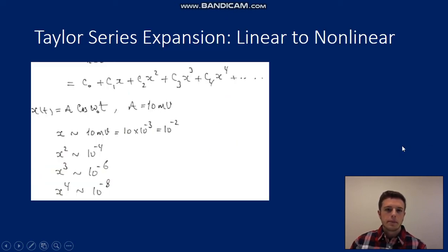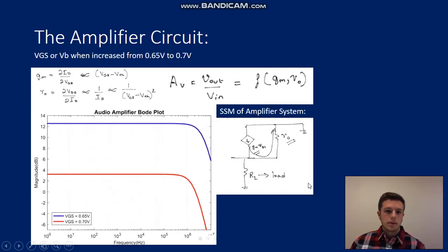Fourier series equivalent. Now by Taylor series expansion we will show that it goes from linear to nonlinear, with A being 10 millivolts, that is our X in this case, out of the Taylor series expansion. And you see as you go up in higher order terms of X, these become negligible. That is not the case at 200 millivolts, as it is still a large value, as seen in the previous distortion graph with your other frequencies in your higher order X terms.